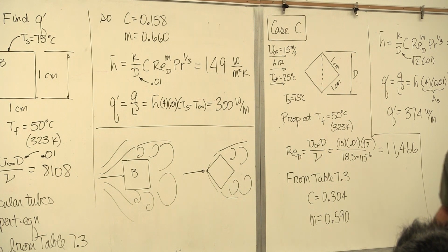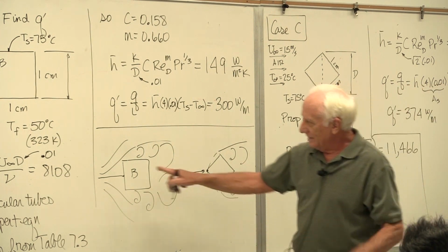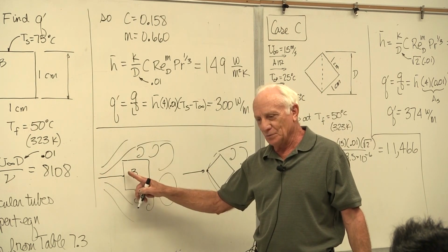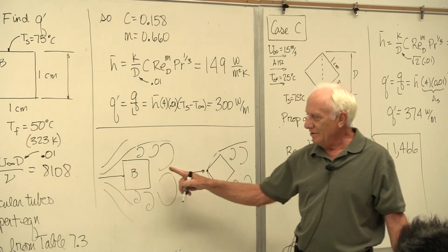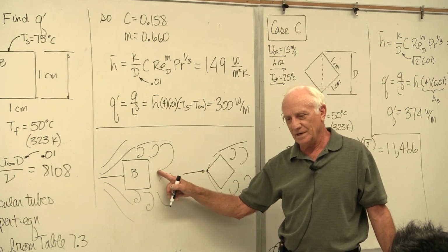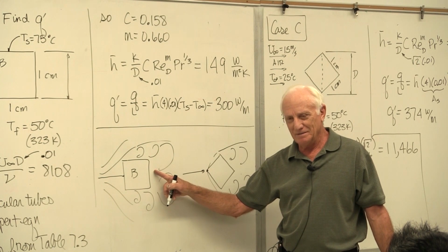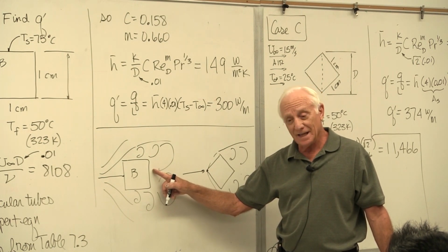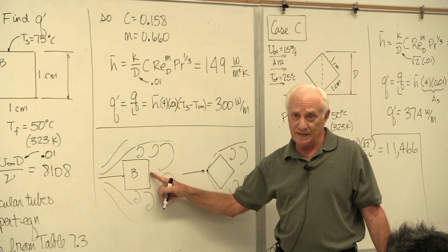The front window is much, much cleaner than the back window because this velocity sweeps any dirt off the front windshield. But on the back, you don't have that. You've got a turbulent wake region, so the dirt sticks back there. And you've got to wipe that window every time you buy gas or whatever. And that means you've got poor heat transfer, because if the air is not moving, I guarantee you the heat transfer is not very good.